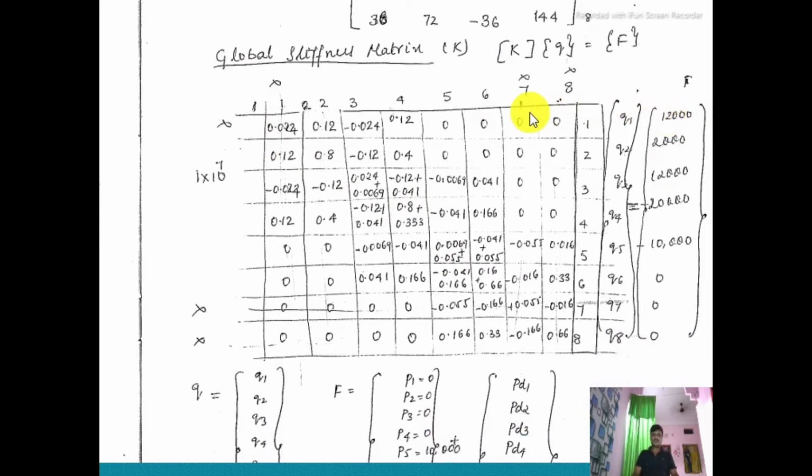So this is K. Now finally we will get the K. Again this is the Q value, that is the displacement, the deformation at each node. So here Q1, Q2 is taken. Q1, Q2 is nothing but, whatever the odd numbers are, those are the vertical displacement, and the even numbers are the rotation displacement. Or if you are still getting confused, you can go for V and theta. In many textbooks it is referred to as V being the vertical displacement and theta the rotation.